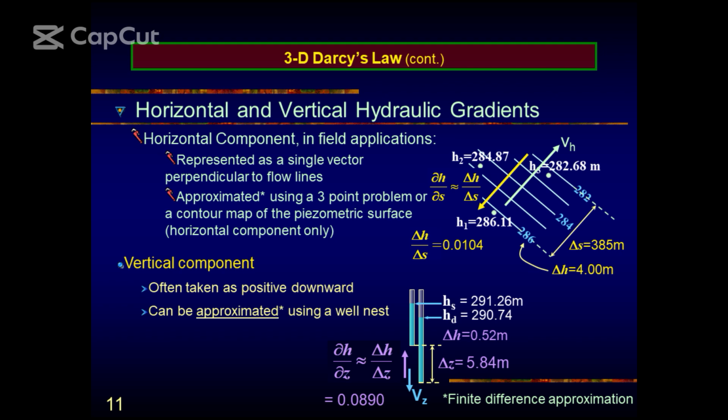600 plus, right? So let's say about 600 meters. And then when you sink your piezometer, or when you measure the depth from this level to the top of the water, let's say it is 3 meters. So what is the pressure head or the piezometric head? It will be 600 minus 3, right? Which is 597, right? So this is the head, isn't it? So that is how these heads are determined. Are you following?